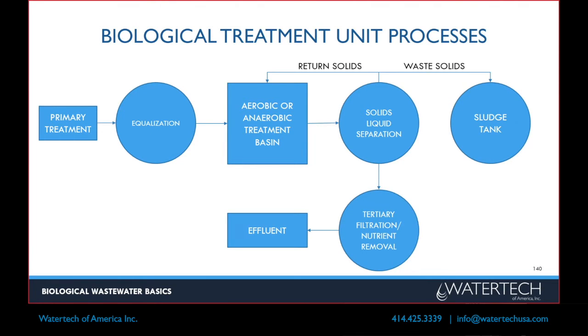So what we do have to do is take a certain portion of these return solids, waste them into a sludge tank for disposal. It'll go to landfills. It'll go sometimes on fields, farm fields as fertilizer. And then that step 2, dewatering. This is usually going to be liquid. If you can't handle that much liquid out on farm fields or whatever, then you can dewater it, basically reduce the amount of volume that you have.